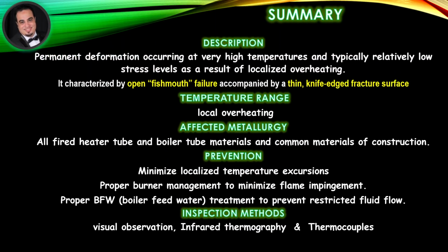Short-term overheating stress rupture, including steam blanketing. Summary. Description. Permanent deformation occurring at very high temperatures and typically relatively low stress levels as a result of localized overheating. It is characterized by open fishmouth failure accompanied by a thin, knife-edged fracture surface.